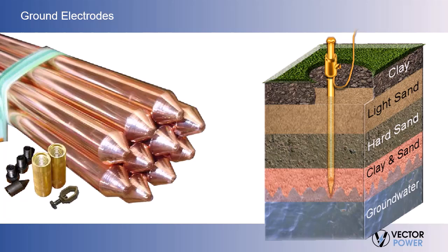Grounding electrodes are usually made of conductive metal, copper or copper clad, with adequate cross sections, so the materials and connections' overall resistance is negligible. Further, the National Institute of Standards and Technology has determined that the resistance between the electrode and the surrounding earth is also negligible if the electrode is free of paint, grease, or other coatings, and if the earth is firmly packed. Therefore, the only component remaining is the resistance of the surrounding earth.